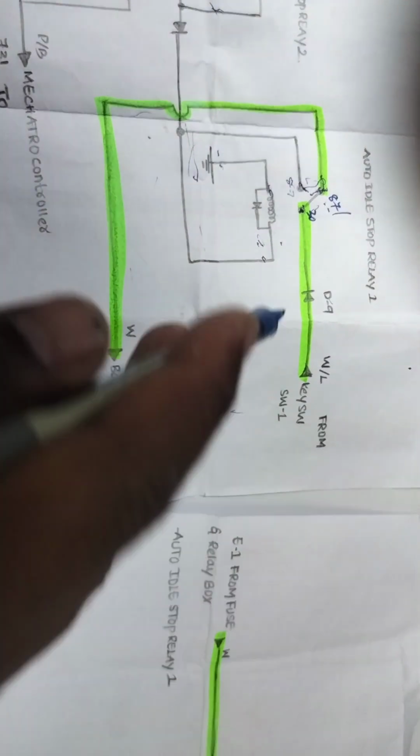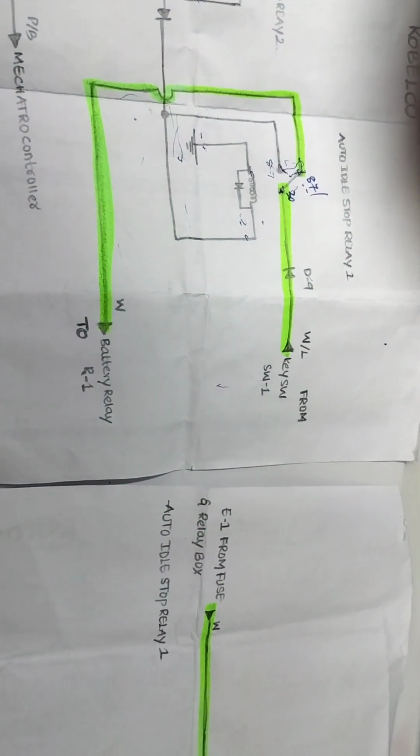Then we check the connectors like that, and so on. So anyway, there are three things you need to check when you don't have any supply. You need to check opens and shorts in the wiring. You need to understand the basic wiring diagram of this one. From the 87 to this terminal, we need to have continuity. If there is no continuity, this indicates we have opens in the wiring.